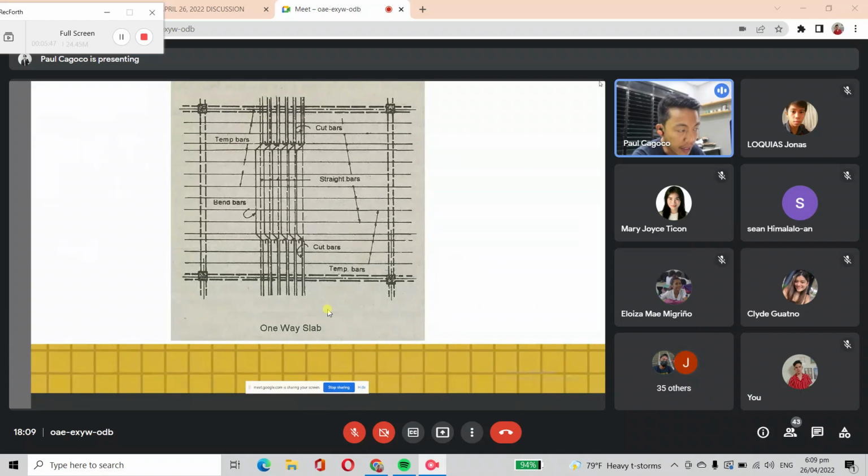As you can see, here where it bends, that is the point of inflection. That point is the limit of the 30 cm. When you look at the top and at the bottom, it is not diagonal. So that's the inflection point. That is the limit of 0.30 meters, your imaginary line. That is as far as your imaginary line goes, which serves as your beam.